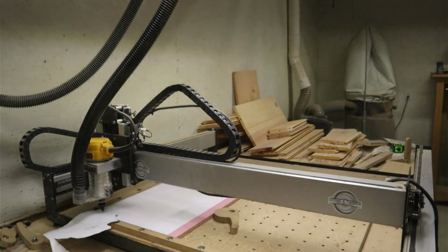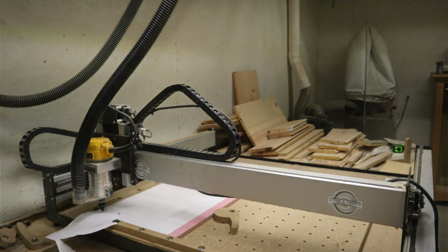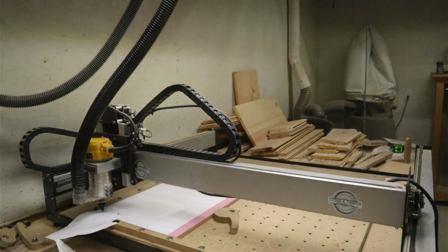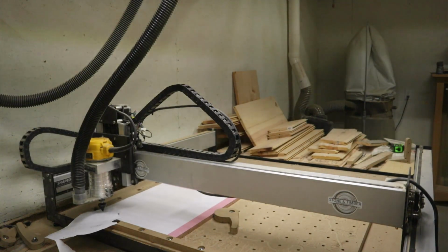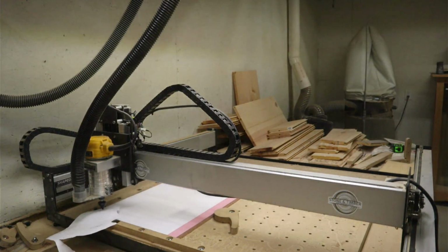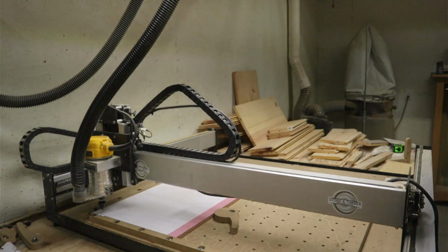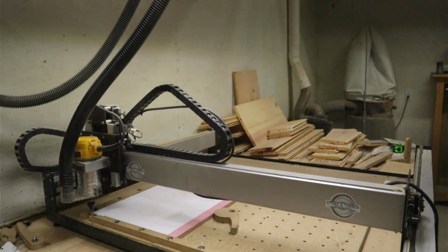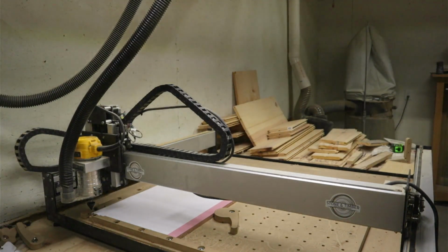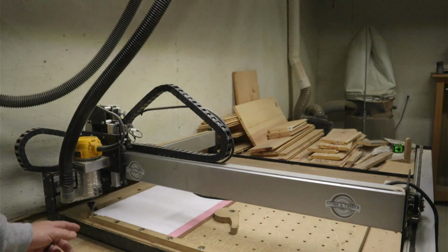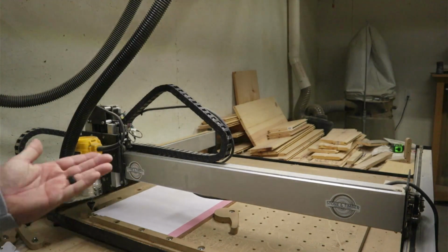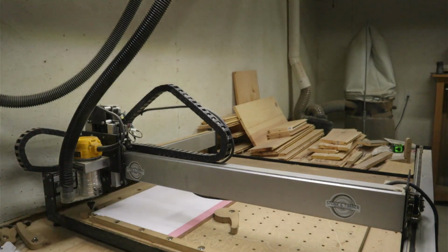Now, my paper's stuck in here. So what I do next is I will go to rapid position, and I go rapid to current Z plus 6 millimeters. I click that first. That raises it up. Now I'll click rapid to current XY, and now we're at a good starting point. If you do that in the opposite order, if you go current XY first, it's going to drag that bit across your workpiece, and you'll probably put a groove in it. So make sure you raise it up first, and then move it to the XY.